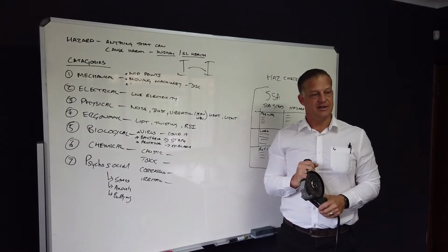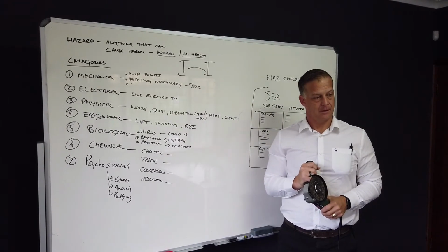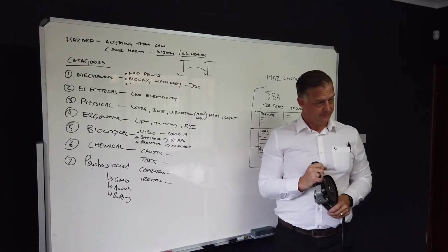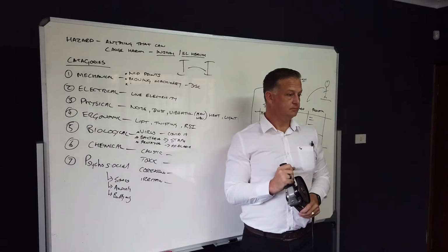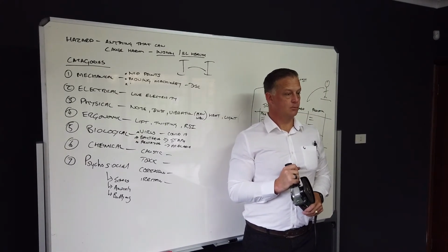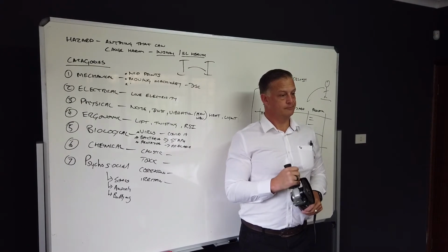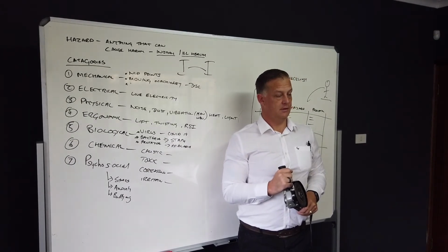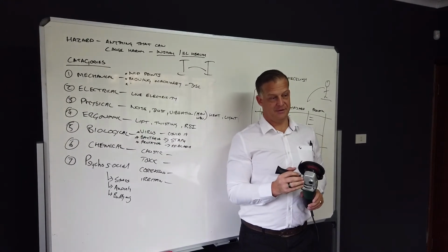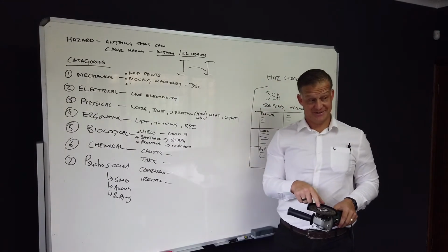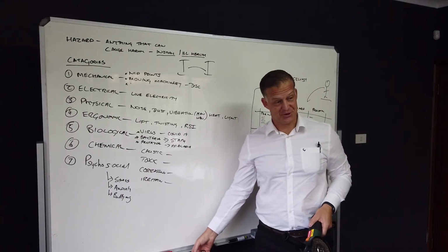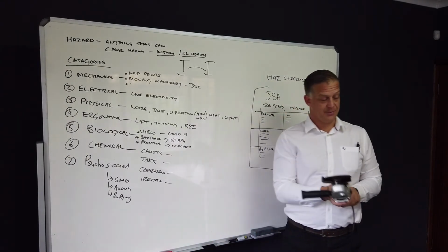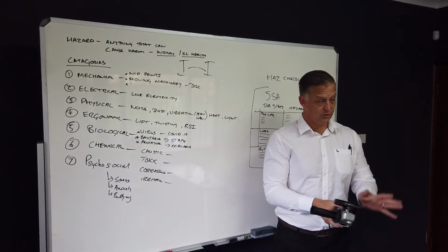What do you think I now need to do? To make sure, when you put back, for example, the angle grinder that you're using, you make sure everything is in place and correct, so you put it away and you pack it, and you clean where you are working. Okay. Make sure it's clean. Okay, do you think this is hot? Yes. Do you think the work surface is hot? Yes. Okay, so we need to make sure that this is allowed to cool and it's safe.